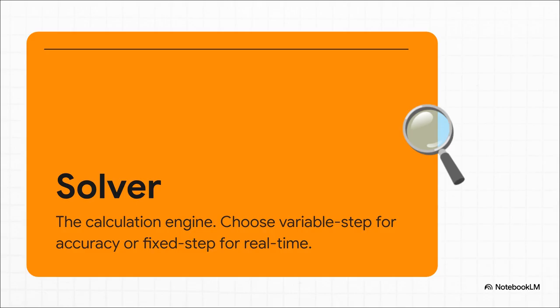Just think of it as the brains of the operation, the math engine that's doing all the hard work behind the scenes. Plex gives you options here. You can use a variable step solver, which is great for getting super high accuracy, or a fixed step solver, which is absolutely essential if you plan on doing real-time testing later on.